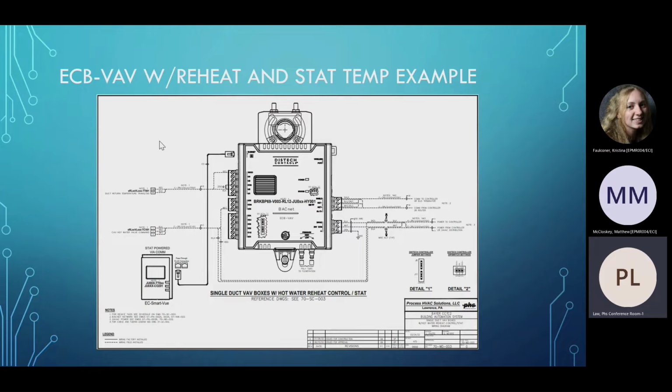Valve is hot water. Yes, there is a cooler. There is, yeah, it's the next one after this one. So this one, it's essentially the same thing, except instead of the temperature, so we do have a temperature probe coming in for the return duct temperature. However, that's going to be ignored. We're going to control the valve based off the temperature that is inside the thermostat. So there's a thermometer inside the thermostat that we're going to use to base the valve position on. And there is a CO2 sensor in the thermostat that, if it's too high, will open all of the air dampers to get the CO2 out of the room.